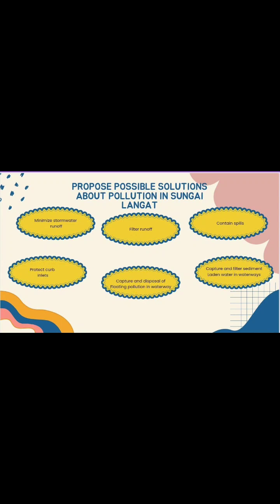When stormwater enters ditches or culverts, a check dam or ditches can be used to filter the runoff, preventing sediment from entering water such as ponds, drains, and holding areas. It can be filtered using dewatering products in which water is pumped into the bag, capturing any sediment and releasing the water.